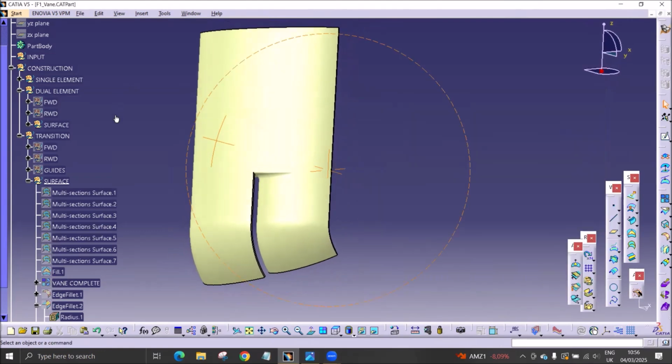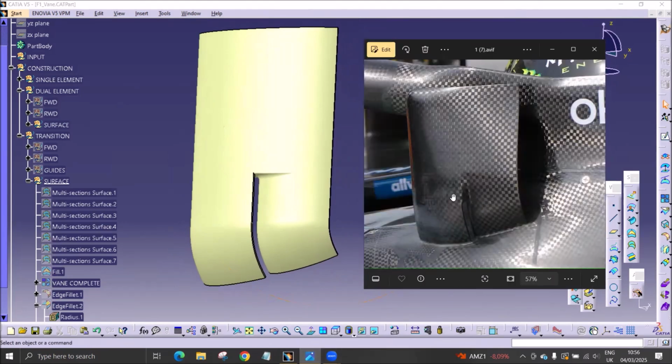If we look at the McLaren one, you can see the bumpy surface. You can see how the trailing edge between the two elements is closed, which creates huge separations, which will travel downstream. And I mean, it's just how it sometimes is in these development departments. You want to get something quickly out of the door. You have a new joiner. They quickly get it done, or as quick as possible. The numbers in CFD and in the wind tunnel are not so bad, so you just quickly get it out to the track. And then something like this ends up at the car.